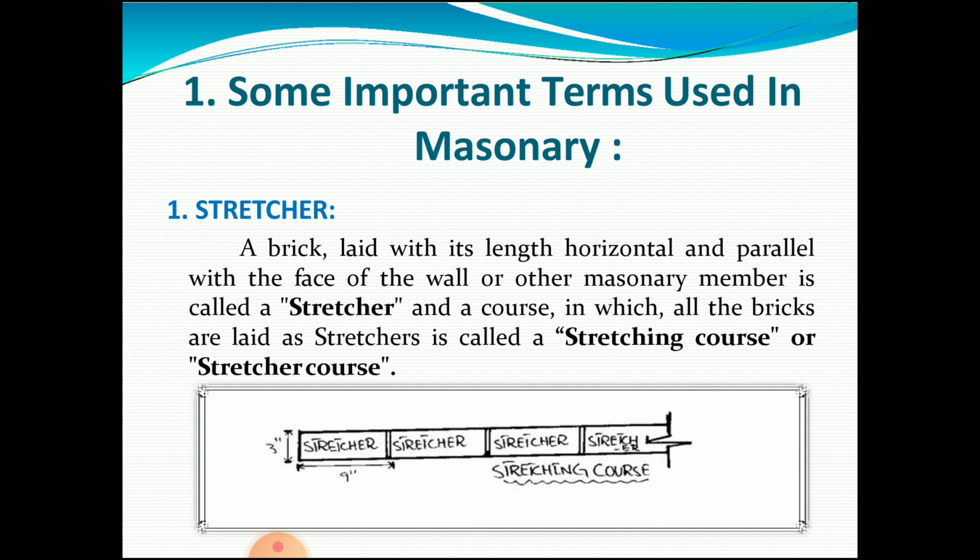If you look at the picture, if you look at the figure, you will clearly get the idea. The brick which is laid with its length horizontal and parallel with the face is called a stretcher, and the course which is laid that way is called a stretching course or stretcher course.